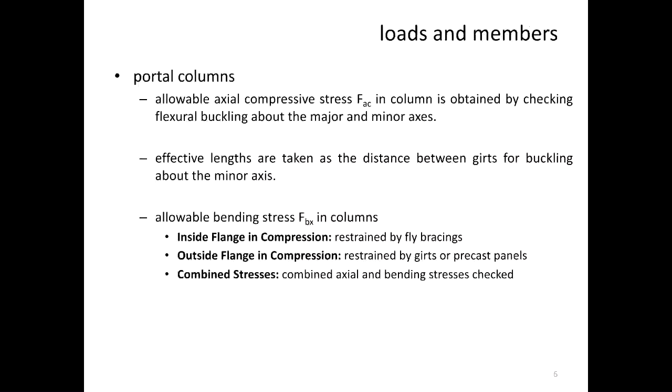Another aspect of that as well is protection. When you have a precast panel, that lower part of the structure, the precast panel might go up to maybe 2.4 meters high, and then the rest becomes lightweight cladding. So if you have forklifts in a warehouse running around, if the forklift loses its control, it will run into the precast panel and it's still safe. But if it was lightweight all the way down to the ground, then it can get damaged.